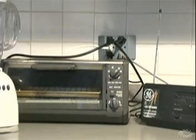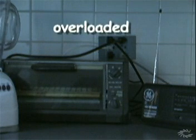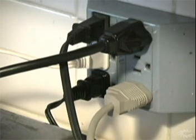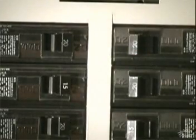You may have experienced that when using a bunch of electrical devices at the same time. Suddenly, everything stops. That's an indication that the circuit has been overloaded and the amperage has risen above the circuit's limit. This is a safeguard because the wires in the circuit have been getting hotter and hotter, and if the circuit breaker didn't trip, a fire might have resulted. To correct the situation when everything shuts down, unplug some of the appliances and then reset the circuit breaker by flipping it back to the on position.